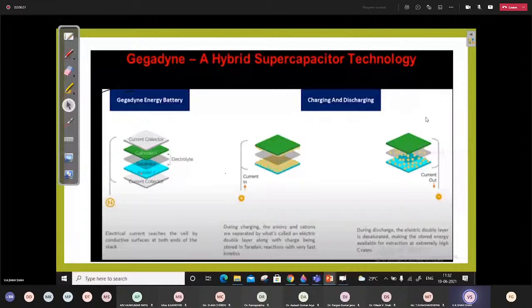Now, as I have told you, the supercapacitor has different characteristics and the battery has different characteristics, and we combine these two storage devices together to meet the power and energy needs of a vehicle. That's why we need a hybrid power source. Designing a single power supply source to meet a peak load demand leads to an uneconomical and inefficient design. A better approach is to have different sources for different sections of the load demand, because the load demand profile differs: accelerating, constant speed, and deceleration.